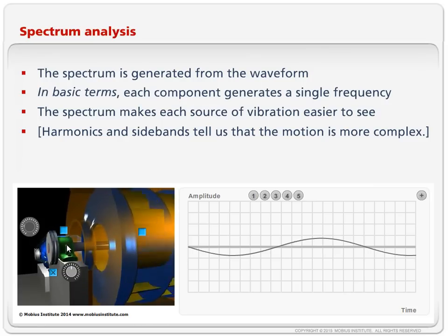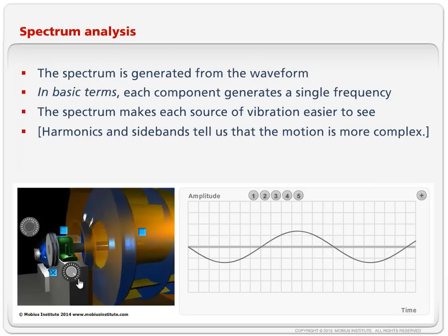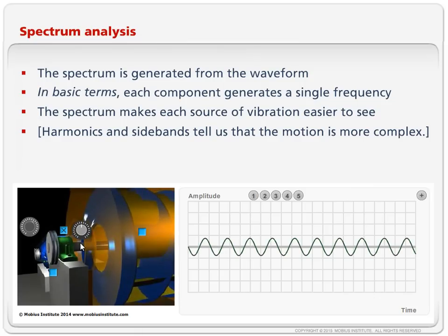So there is the vibration at the running speed, at the once per revolution frequency. If I speed up the machine, then like we saw just before, the waves get a bit closer together. If I have more amplitude, I get a bigger signal. So from this grey shaft, I've got this grey vibration. That's sort of what we saw a moment ago. I'm going to turn that off, and let's have a look at the green bearing now. And lo and behold, now I've got green vibration, but it's clearly a different frequency.